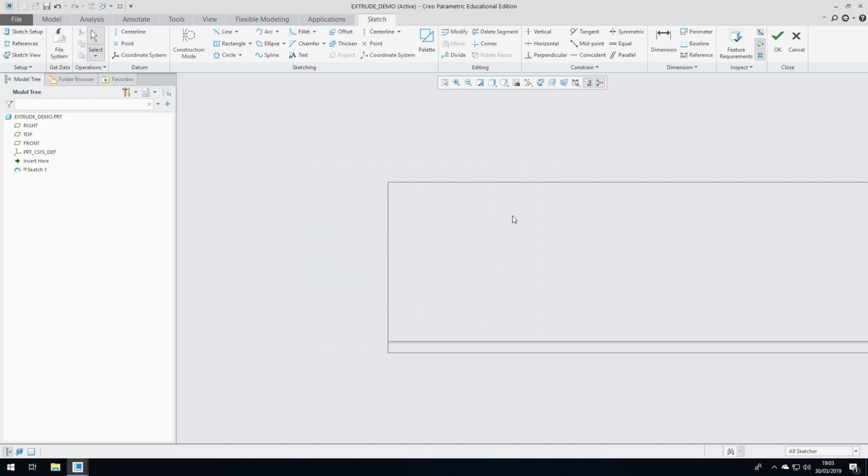So we'll delete those. So again, that's the circle function. Arc, you can just do a section of a circle. So you can almost effectively set four semicircles with whatever radius you want on the side of them and whatever angle you like. So simple function is the arc function.